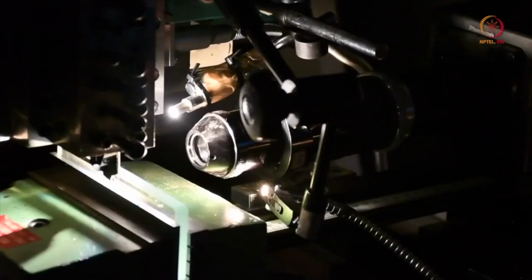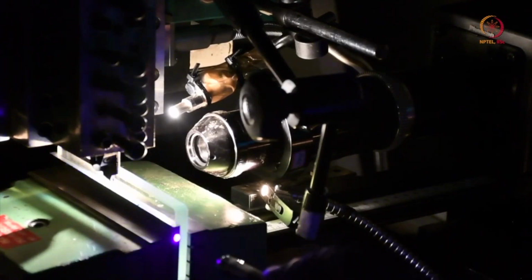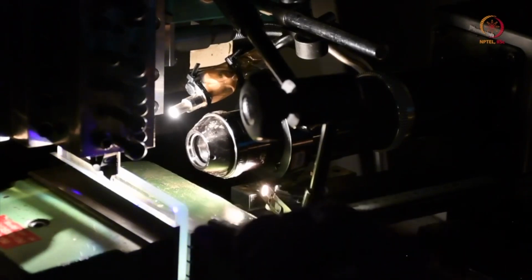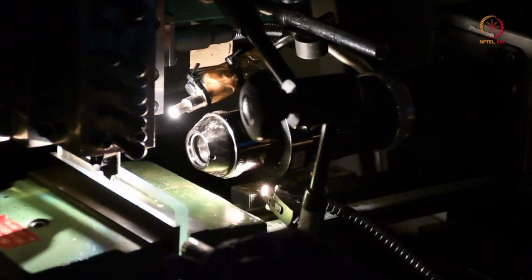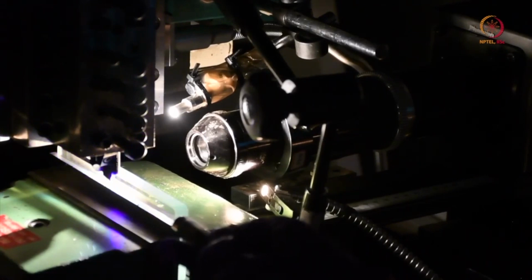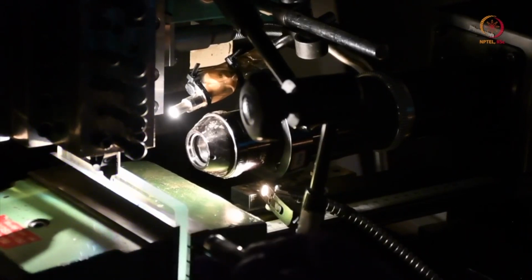So let us look at the components of this experimental setup. First thing is a specimen. We have an aluminium specimen here. On this specimen I have created speckle patterns using emery paper as I showed you. Now this specimen is moving against this stationary tool. As a result of this movement, this specimen will deform and will result in chip formation, and we call this process a machining process.